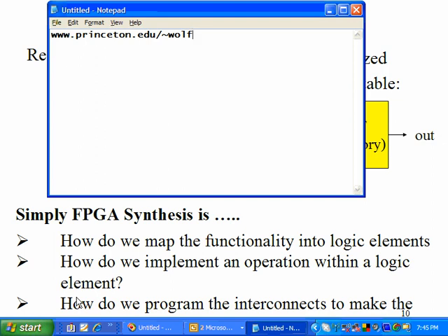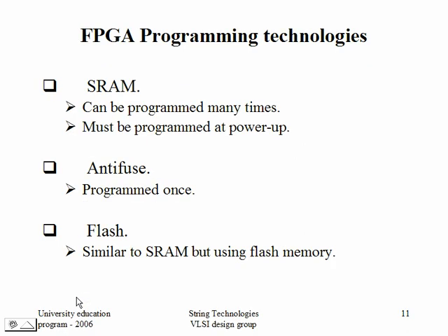Now I'm going a bit into different FPGA technologies. Like he might have told, some microcontrollers come with inbuilt flash, some come with different variations. FPGAs also come in different flavors. SRAM based FPGA, so the idea is what? SRAM, anybody knows what is SRAM? Static RAM, isn't it? It is one type of read-write memory. Now another type of FPGA is called anti-fuse based FPGA.